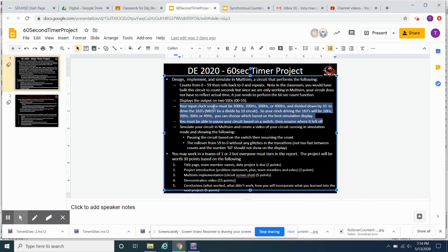If we were to do this divide by 10, how could we do it? Well, we know that with our D flip-flops or our JK flip-flops, we can generate divide by any power of 2. We could do a divide by 2. We've looked at that by doing a feedback on our D flip-flop, say from the Q prime or the Q bar output back into the D input. Whatever clock we run that with, it will be that divided by 2.